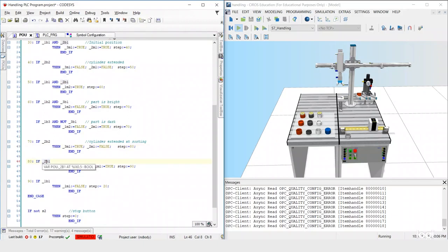So you can see that this is actually a step-by-step approach, which is unimaginable in ladder logic. This can only be achieved with 2 programming languages, or rather 3. This can be done with structured text, it can be done with sequential function chart, and also it can be done with statement list. I'm not saying that you cannot absolutely do it in ladder. What I'm saying is that it becomes very difficult to do it in ladder, because ladder does not have a step sequence like this. So you have to use a lot of flags, a lot of relays for that.